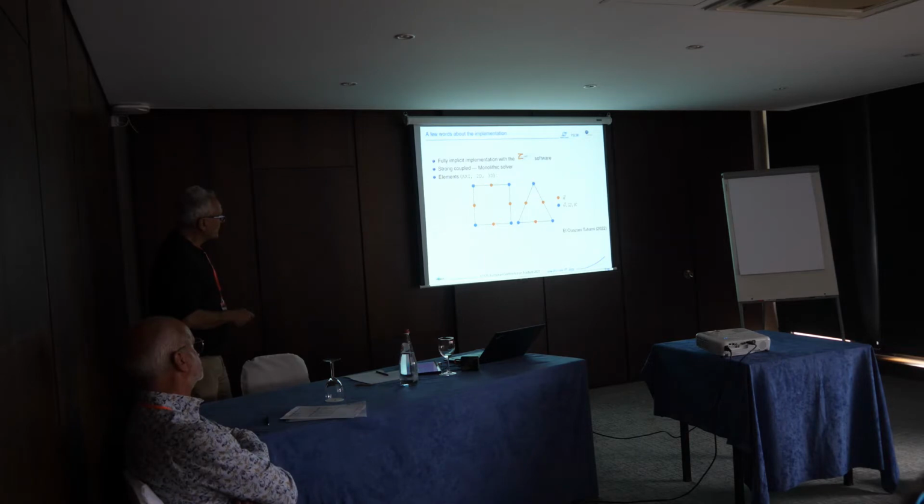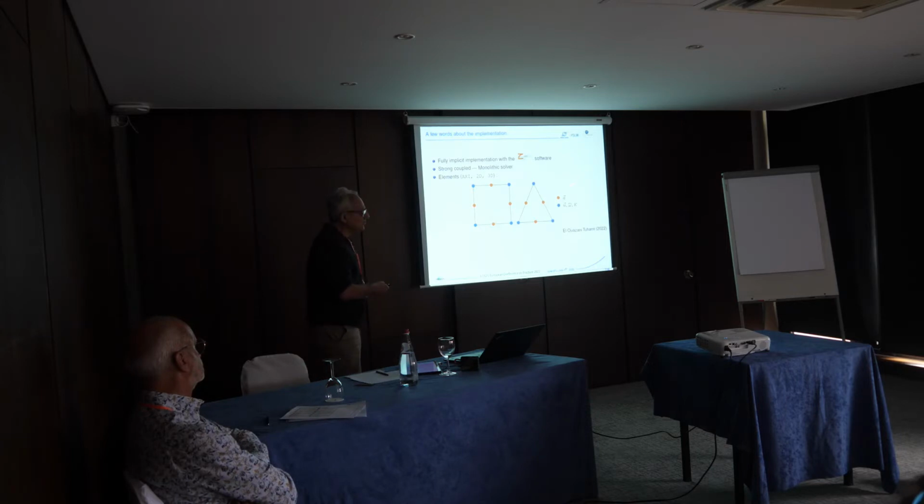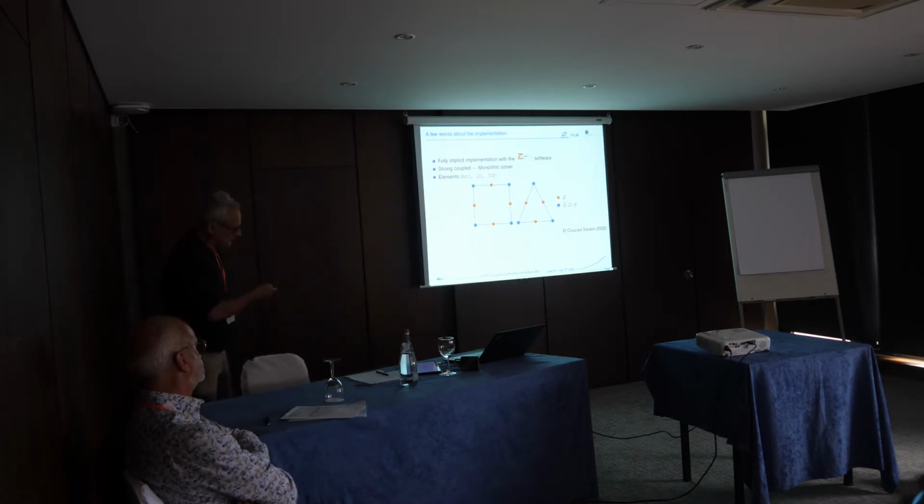We use quadratic interpolation for displacement and linear interpolation for the non-local variables omega bar and kappa bar. So the cost of having these non-local variables is not so high because they are interpolated using linear functions, whereas displacements are interpolated using quadratic shape functions.